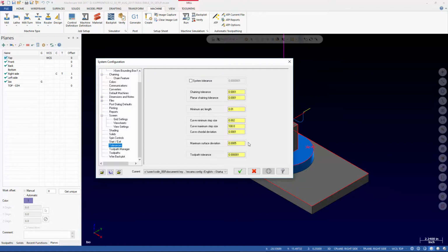And now if you've taken all this geometry and you've now rotated it and translated it in space, is all this stuff relative to that new plane, or is this all relative to the Mastercam world? Well, they'll tell you it's supposed to work with the WCS, but these are some of the kind of problems that have cropped up in the past. It will simplify your life greatly.